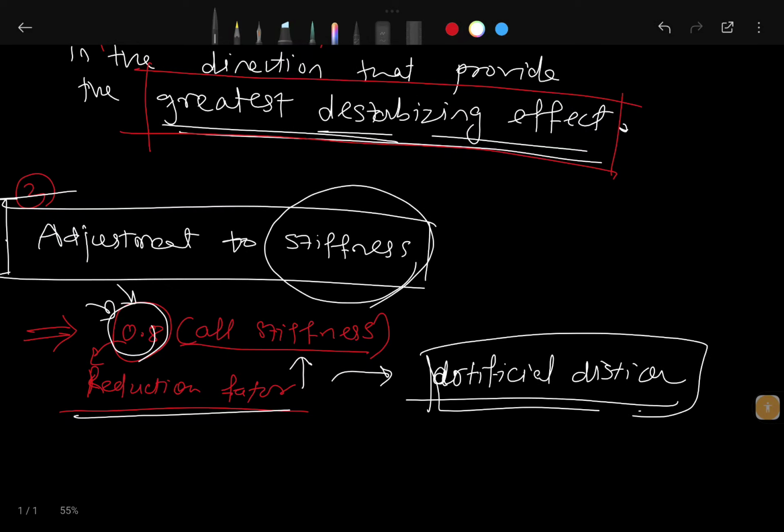Okay, now you can get this point. An additional factor shall be applied to the flexural stiffness of all members whose flexural stiffness is considered to contribute to the stability of the structure. For non-composite members, tau-b shall be applied. There are different conditions we have taken for this adjustment to stiffness. These are covered in AISC 360. If you want detail, then we can take this in a lecture.